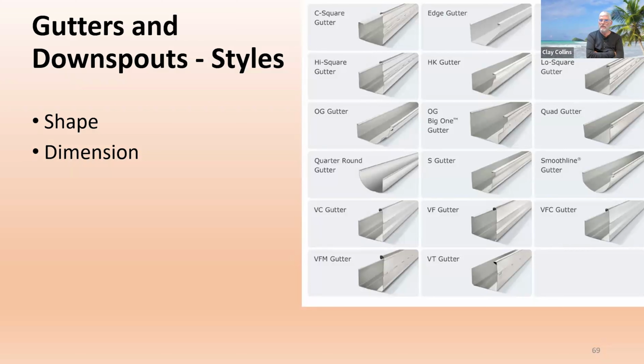If you look at the edge gutter, which is the top center, you see that the leading edge is curled over. And that's just to keep it from being sharp. So it's the back edge that's against your fascia. So you come out here to the C square on the left, top left. And basically a lot of them, the high side is away from the house so that high volume runoff won't overshoot the gutter. But that means with no excluder there, all that first wash takes all that debris down in there. And that's going to block your downspouts.